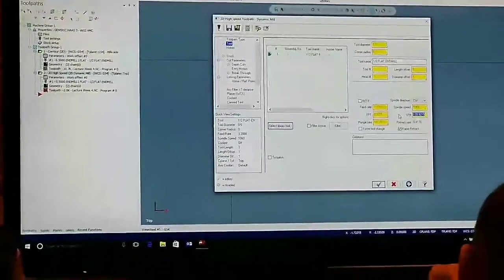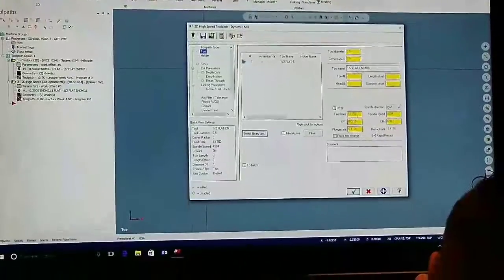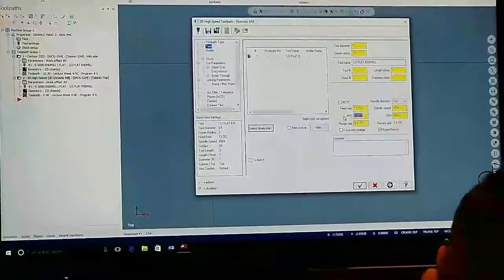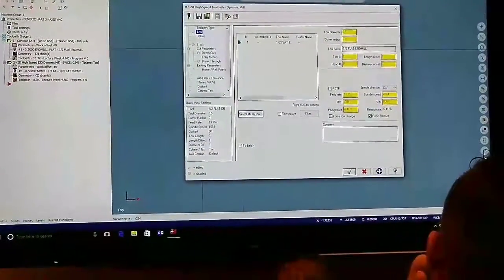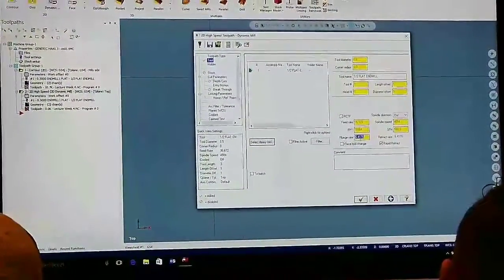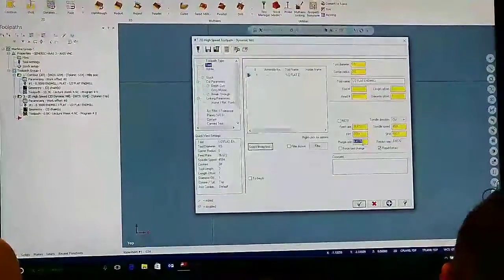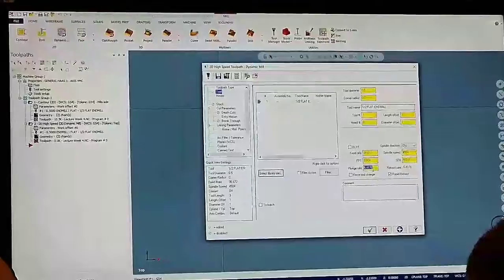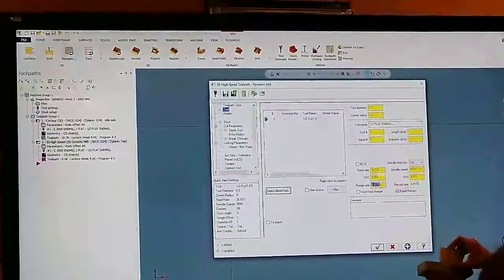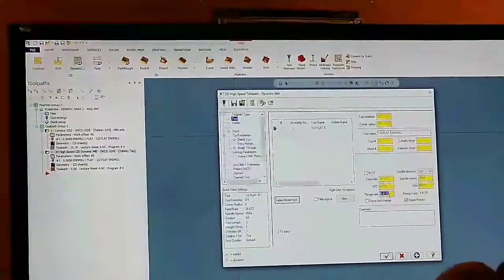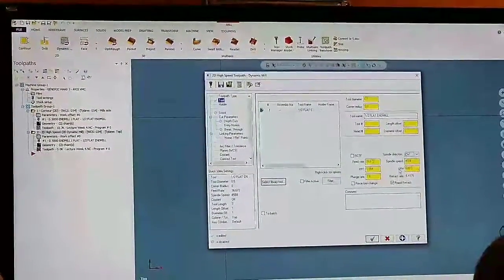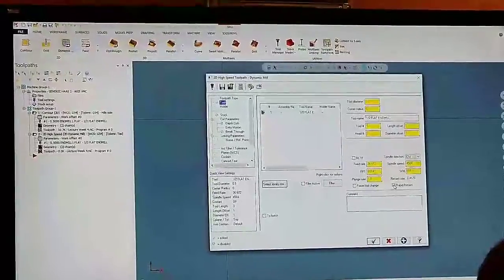So we're going to have to go back in here and set our speeds and feeds. 600 surface footage, and the chip load, I'm sorry. We had 4,000, so we'll leave that at 4. And we're plunging. We are still going to come down into the jaw, because in the center of this, if we have my material, I still have jaw there, so I still have to worry about that the first time. So I will slow that down again as a plunge rate, just put it at 1. And then the retract is already on rapid, so I'm happy with that.